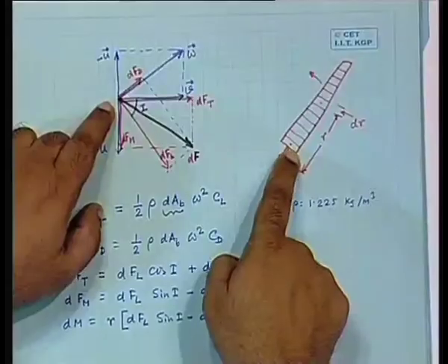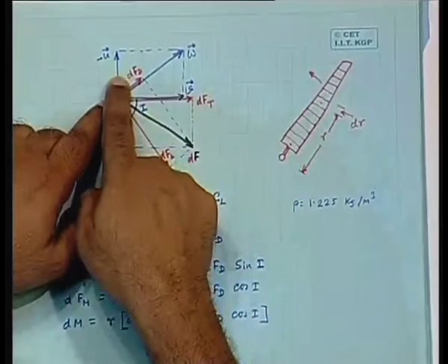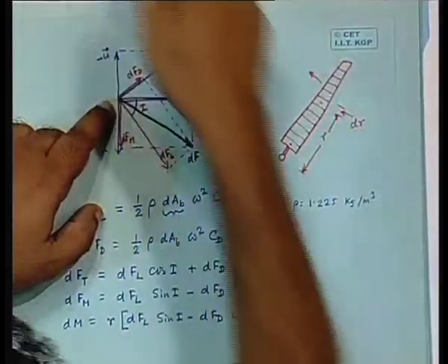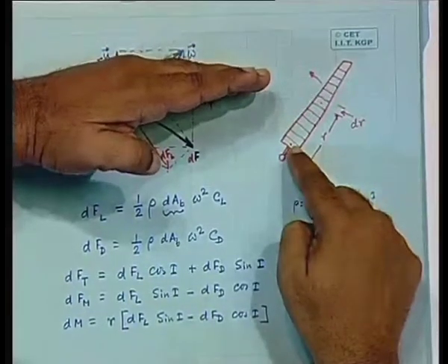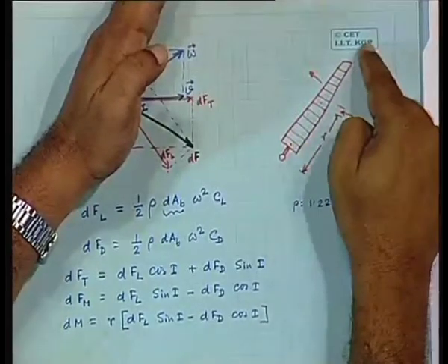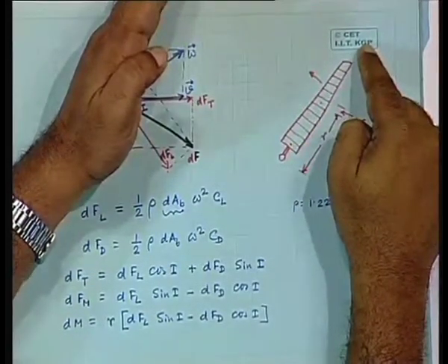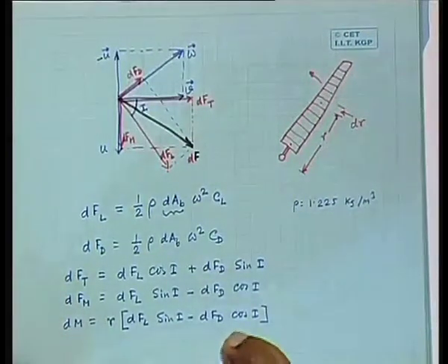The other thing is that we generally produce a twist. Twist means the pitch angle at which it is inclined need not be the same. In fact, it should not be the same. Why? Because inside the u will be small, outside the u will be large, and therefore this w will be more inclined toward the inside, and more toward the outside. Okay, fine. Now, normally you would like to have as little drag produced as possible.